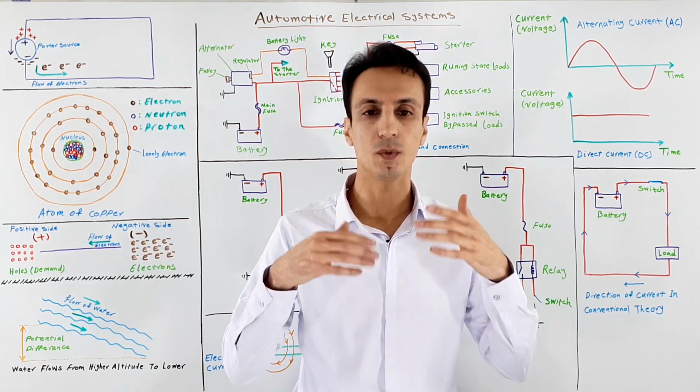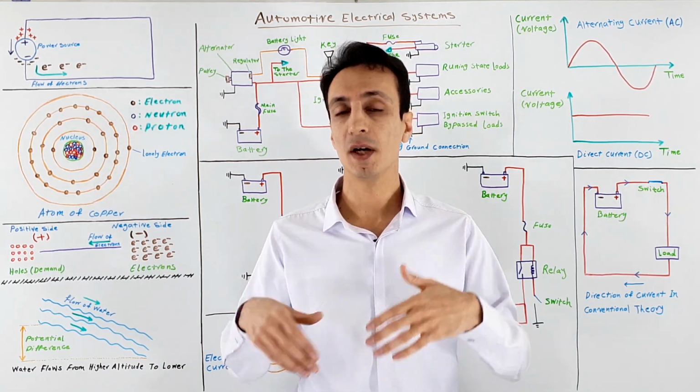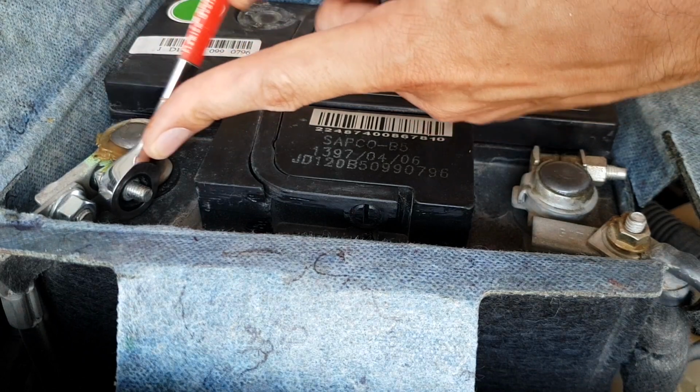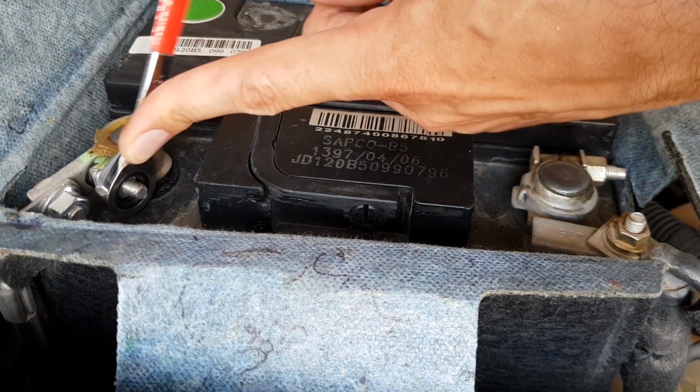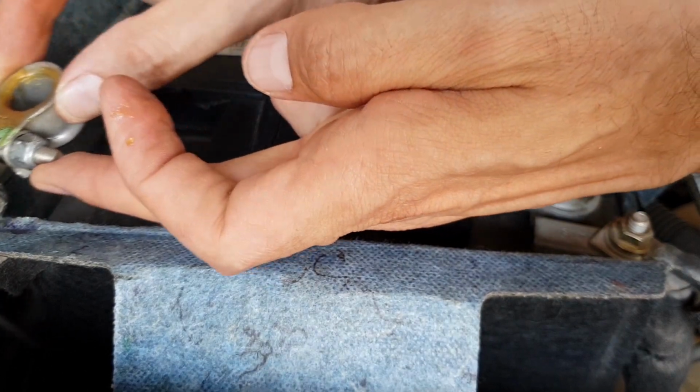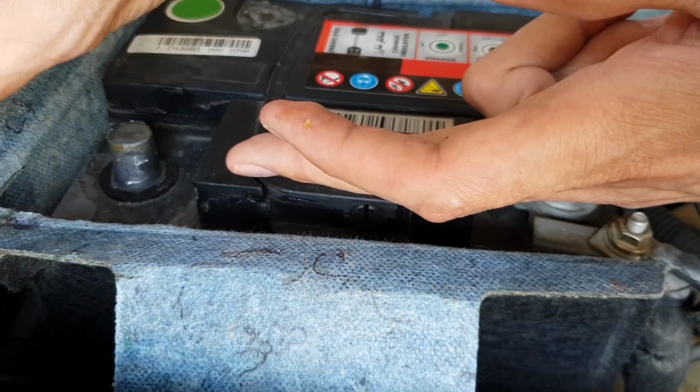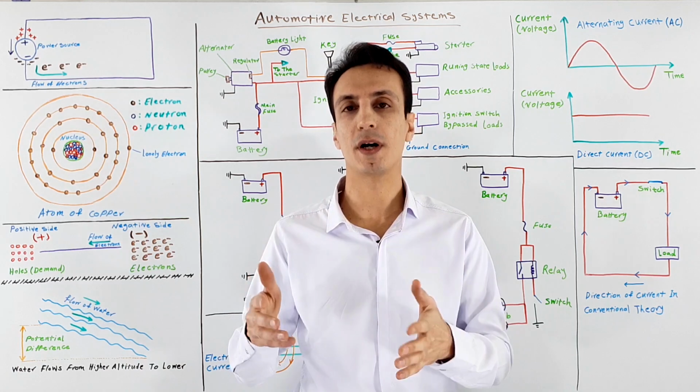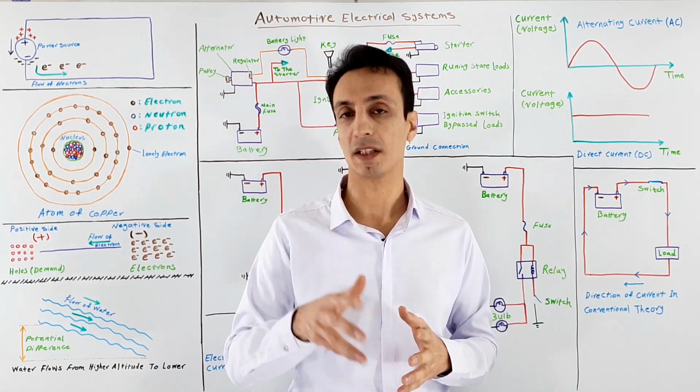And remember that when you want to work on electrical systems, wisely remove the battery negative connection, or to avoid ECU memory loss, you can neutralize that system by removing the related fuse for that circuit. Not following this precaution can cause sparks, blown fuses, and then can make a fire.